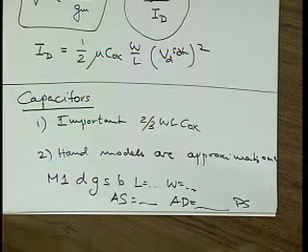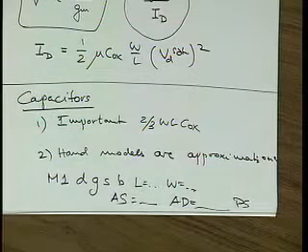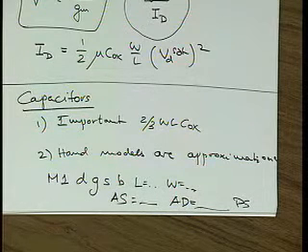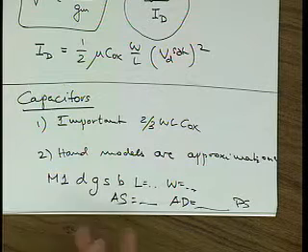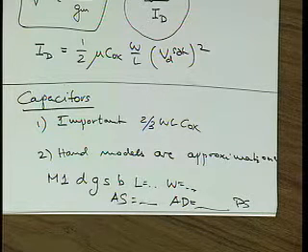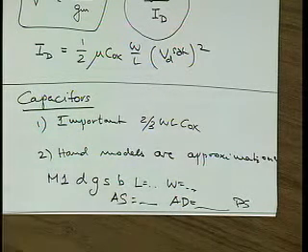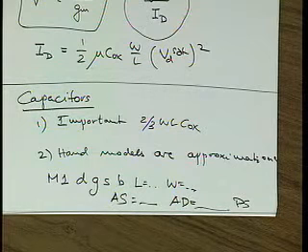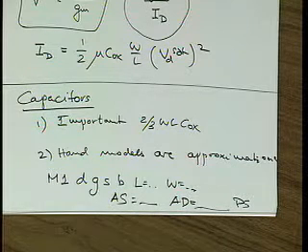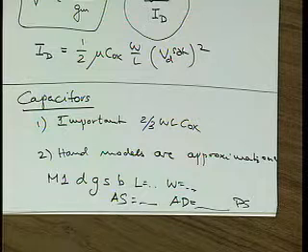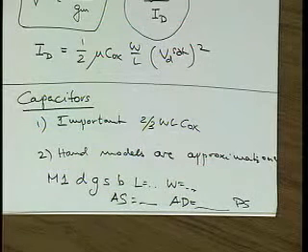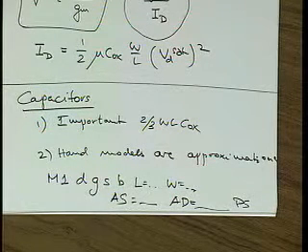Well, first I sort of ignore all these second order effects. Well, these things are not going to be second order very often. And if you don't include these parasitics in your circuit, then SPICE will say, well, everything goes just fine. It's actually even faster than you need it. But then when you stick all of that stuff in, of course, the circuit's not going to meet specs. And you have to start from scratch designing it again.